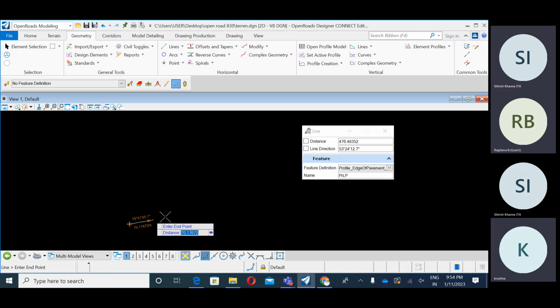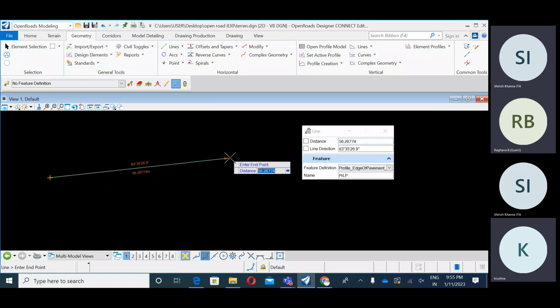The dimension, see, I'm taking it too small, like here. Now see, it is 56.18928 meter. Why are 5 digits there? This data is available while we are not changing the precision. If you want to change it, you can go to your backstage and change the working unit precision. You get the 2-digit value 0.12, and now here we have 0.12345. 5 digits are available.